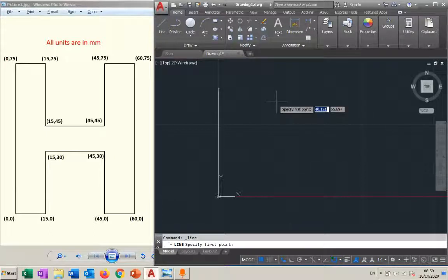There is another way, but let's say we're gonna start with the coordinate 0, 75. Look, again, this is a starting point. When I say starting point, we start the line with that point. Look, I activate line, press escape, I activate line. Now this will be my first point, so I don't need hashtag. I just write 0, 75, hit enter. It will go and click at that point and continue. The rest will go with hashtag 15, 75, and I can continue the rest of them.